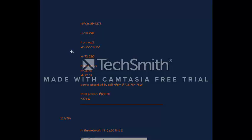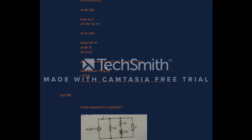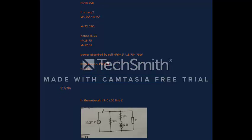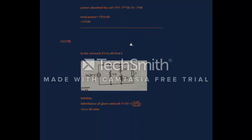From equation 2, XL square is equal to 75 square minus 18.75 square, so XL is equal to 72.62 ohms. Hence, ZL is 75, RL is 18.75, and XL is 72.62. Power absorbed by the coil is I square RL, which is 2 square into 18.75, equal to 75 watts. Total power is I square times (R1 plus RL), which is equal to 275 watts. So that's the total power of the circuit, 275 watts.